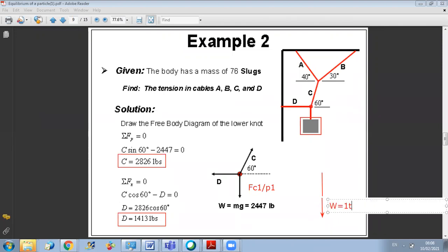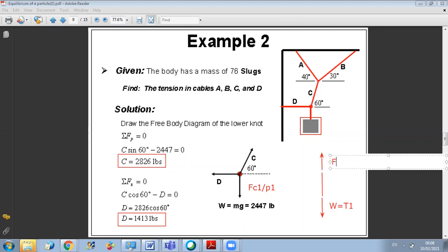And from this side, since it's a cable in tension and in equilibrium, it's a massless cable. So no weight for the cable then. The tension is uniform across any point of the cable. So this is the force of point 1 on cable 1. And by action-reaction, the force of the cable on the point will be equal in magnitude, opposite in direction.